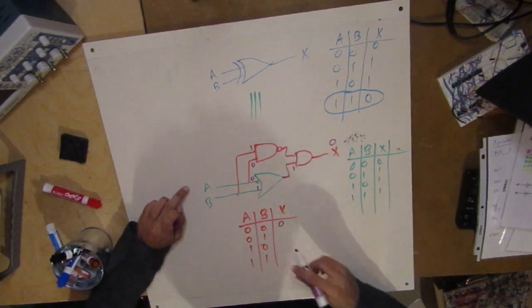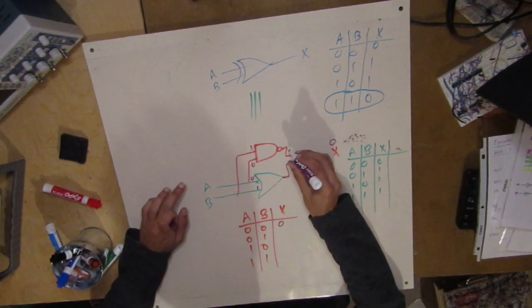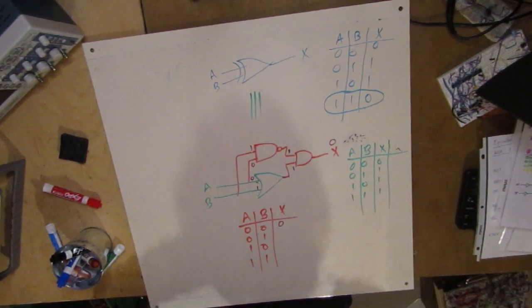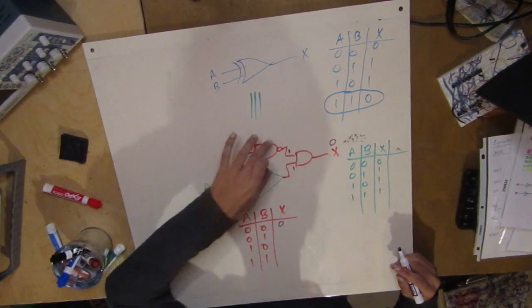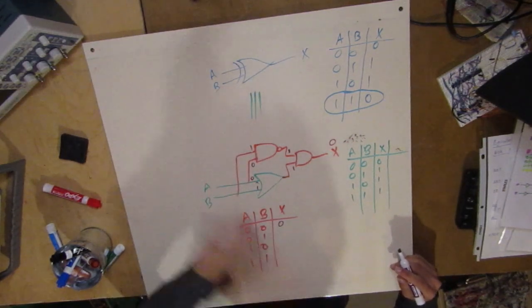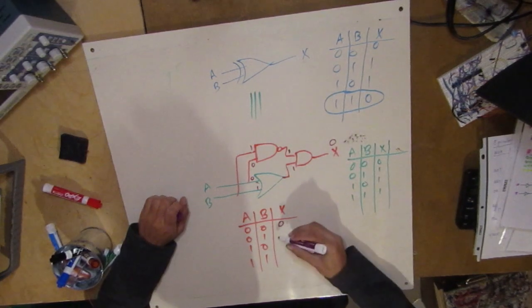We automatically get a 1 coming in like that. Okay? But if we have a 0, 1, we're also going to get a 1. Just check the NAND truth table. The NAND is an OR gate that's looking for a 0. So this is an OR gate that's treating the zeros as 1. So we're at least getting a 1 coming in. And this satisfies the condition.